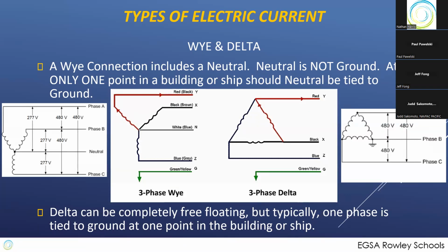And this is going to become important when you are renting additional equipment or when you're doing an initial installation of equipment. Most suppliers of UL listed equipment include a connection between neutral and ground, or a connection between B phase and ground if they're selling it as a delta connection. However, in your whole facility, you want only one connection between those two. So you need to remove the extra cable.